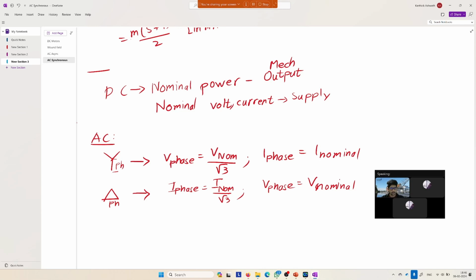Again, in the equations we have terminal voltage and induced voltage. Induced voltage is not affected by all this. It's the same, right? Because it's internal to each phase in the system. But if you're thinking induced voltage is basically phase voltage, no, induced voltage is the back EMF.